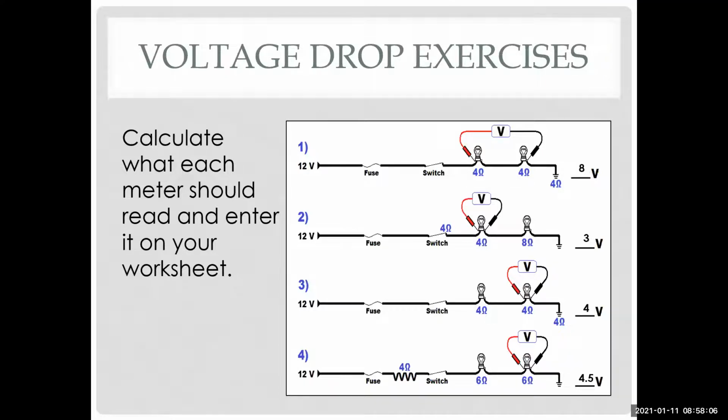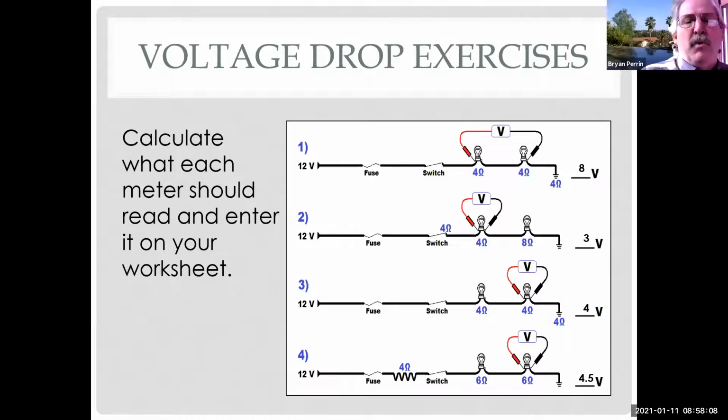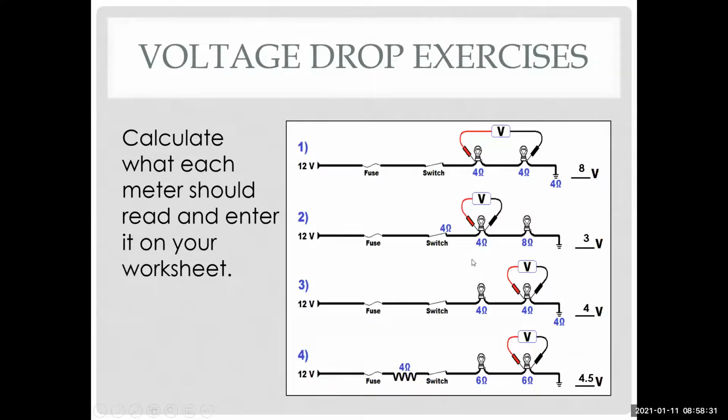Now, if I'm talking the cable that attaches to the starter on the starter side of the solenoid, then yes, I'd see 12 volts key on, engine off, and then I should drop to 200 to 500 millivolts cranking. That's because you're after a switch, and we'll get to that when we get into starters in the next module. Okay, thank you.